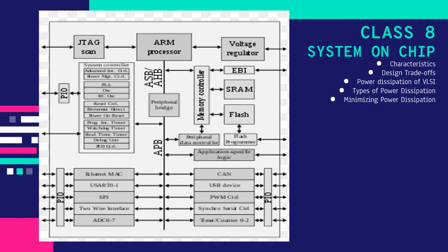We then learned that SoC has certain design trade-offs, or 5 big issues for SoC design, which includes power consumption, chip area, time, reliability, and configurability. We then covered power dissipation in VLSI. We learned about why it matters. The things involved include costs associated with packaging and cooling, standby time and battery life, digital noise immunity, and environmental concerns.